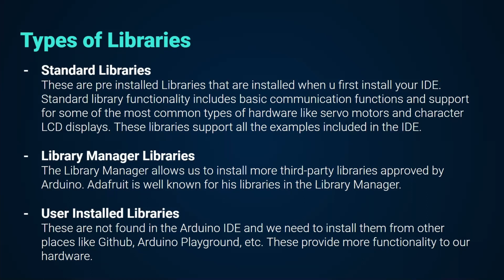Next are library manager libraries, which you have to install from the IDE itself, not from anywhere other than the IDE. We will show you how to install from the manager itself, so don't worry about that. And the third one is user install libraries, which have to be installed externally, and you will not find them in the IDE. You have to find them from GitHub or Arduino Playground.